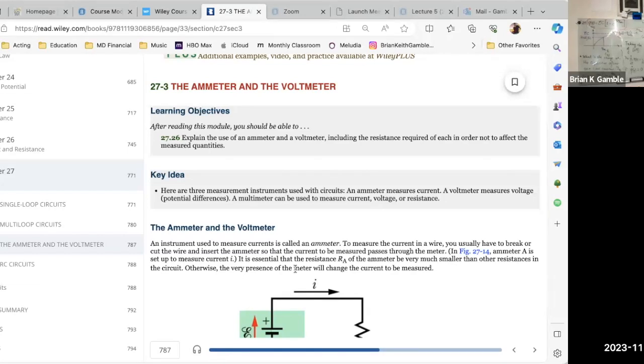Sign convention. By placing the battery in the orientation that we previously chose, we established the positive direction of current to be clockwise, I of t. Since the capacitor drives current in the opposite polarity, we say current is negative from the discharging capacitor as compared to the charging capacitor. Oh, right. Okay. Yeah, there's two negative signs. That's tricky. Because here there's a plus.